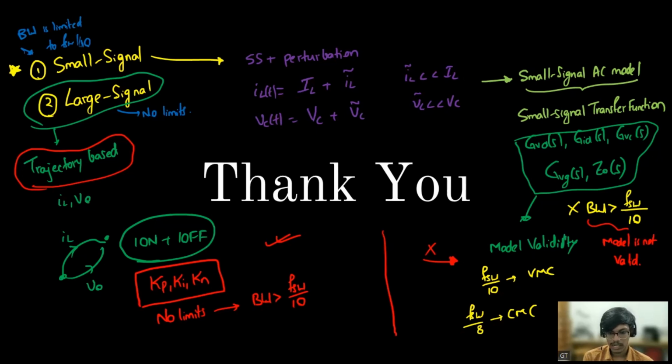So it should be distributed, and the magnitude of each harmonic should be somewhat smaller. SAR has shown the FFT, and when there are harmonics, we have seen that the peaks are not just at the switching frequency and integer multiples of it, but also at fractions of the switching frequency. That's why we call them harmonics. How to distribute these peaks, SAR will discuss in next week's week 12, where SAR will discuss something called spread spectrum.